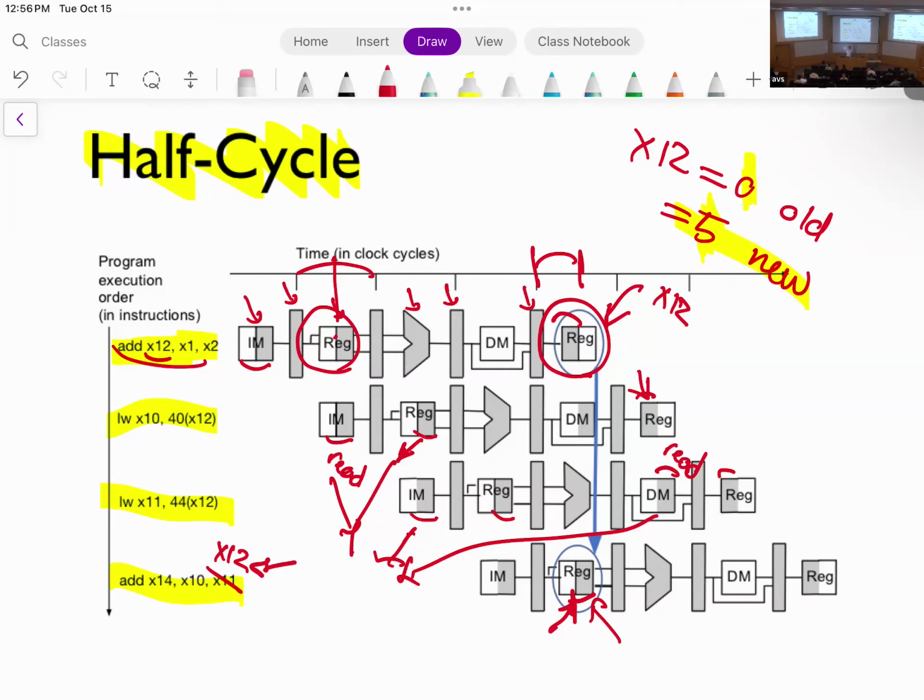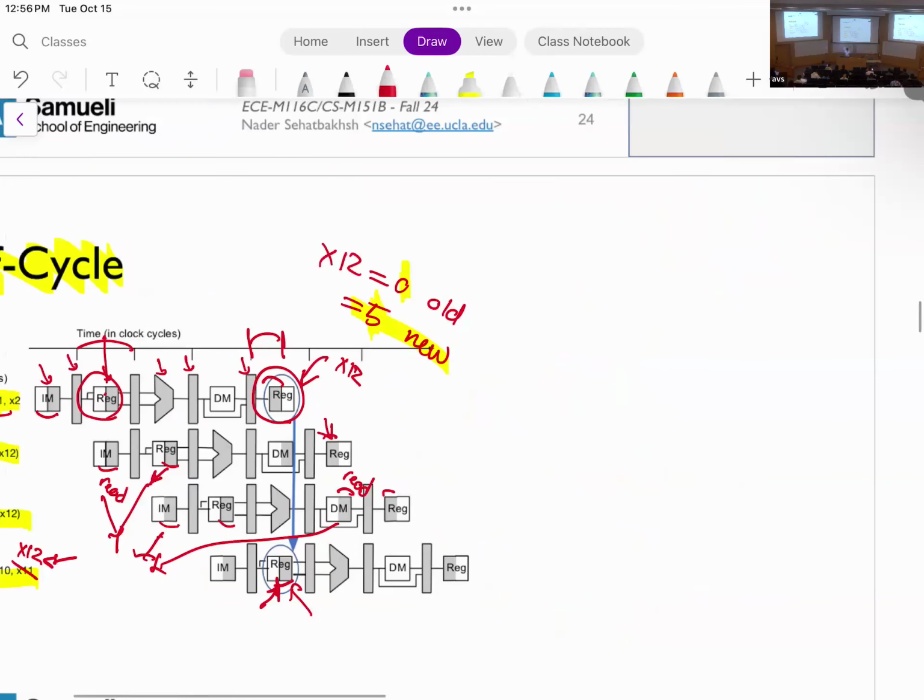Can you repeat the first part of the question? So the question is, if we are making registers out of the flip-flops, how do we really implement this, right? So here's what we're going to do. For flip-flops, you have some delay for writing. Let's say that number is x. If that number is x, I'm going to make sure that my clock cycle is bigger than 2x.